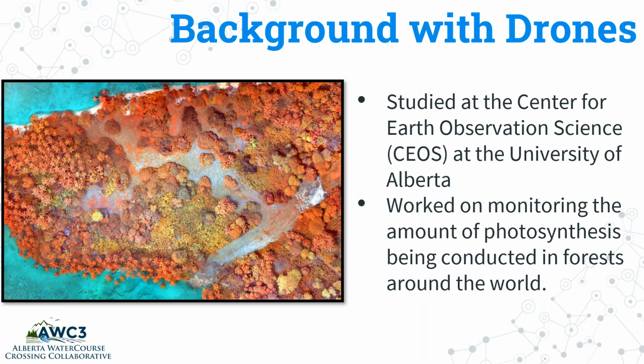And the reason why we are taking photos with overlap is that we are trying to identify common tie points between images so that we can start using those images to stitch them together to form a bigger picture. So typically, when you're trying to create a 3D model, you will take photos of an area in one direction and then photos of that exact same area at a direction 90 degrees to the original orientation. And that just gives you multiple different angles of the same scene, which you can then use to tie together to create that 3D point cloud or that 3D model.